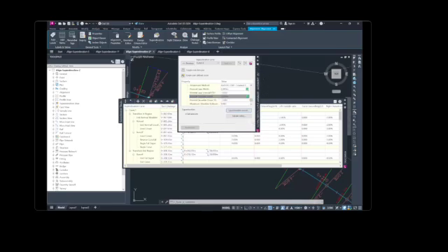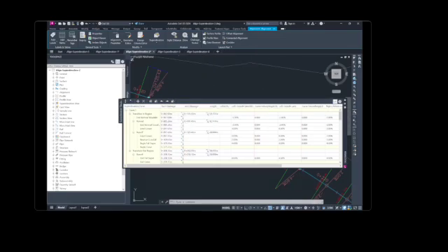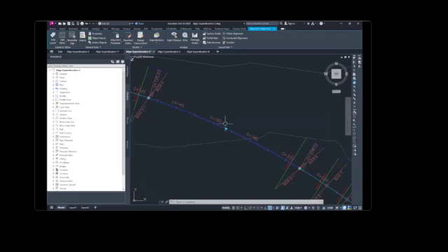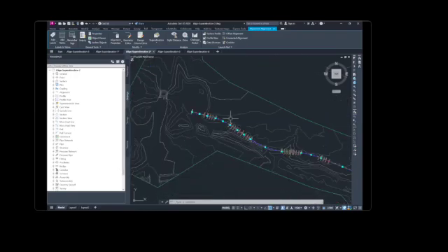So right-click the Superelevation Criteria row, and when this option is applied at this level, the design criteria of the current curve overrides all manual design criteria changes that have been made to the alignment, and then dismiss that. And we're gonna continue